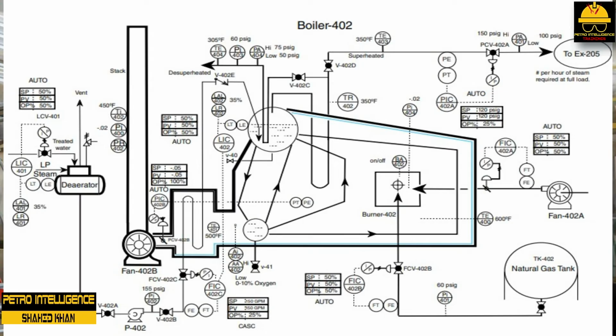Fans provide airflow through the furnace, creating a slight draft or negative pressure. Since the furnace is hotter than the outside air, significant density differences exist. Water temperature increases at programmed rates. Pressure begins to increase inside the large vapor disengaging cavity in the upper drum.